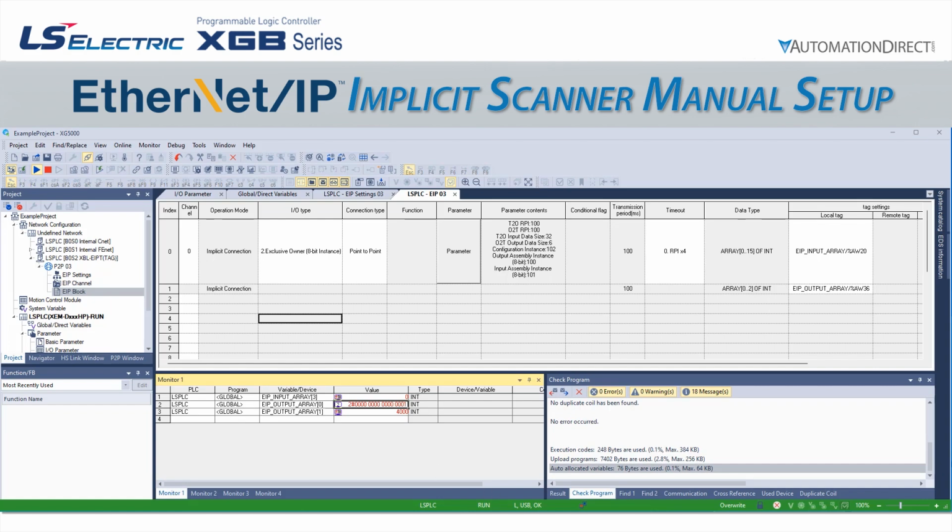Perfect. We have now configured an implicit Ethernet IP connection with the PLC acting as the scanner by manually setting up a message. We can now control our GS20 VFD from the PLC.